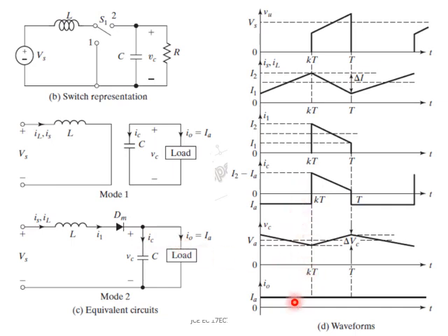Now I0 we are assuming to be fixed DC. So the part other than I0, the ripple, will be taken over by the IC. So IC will be almost like this, equivalent to this, but shifted to negative during the switch on time, and this is the off time.